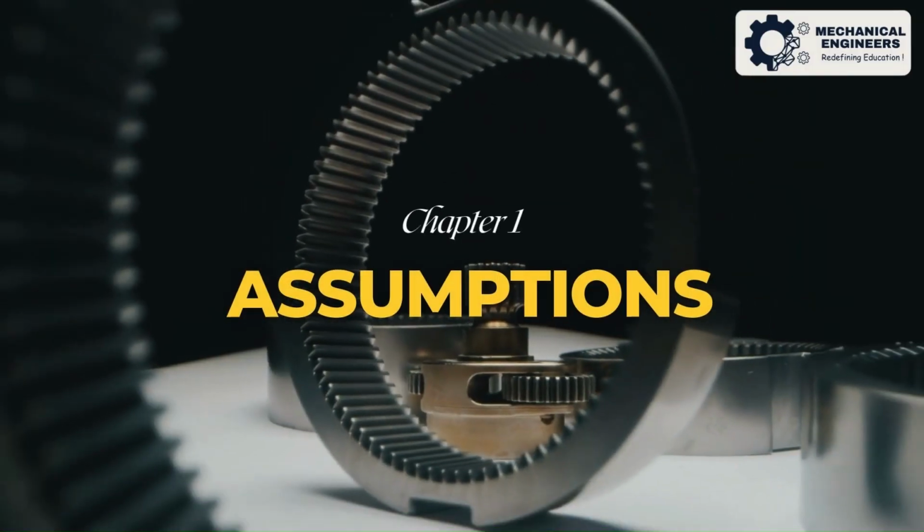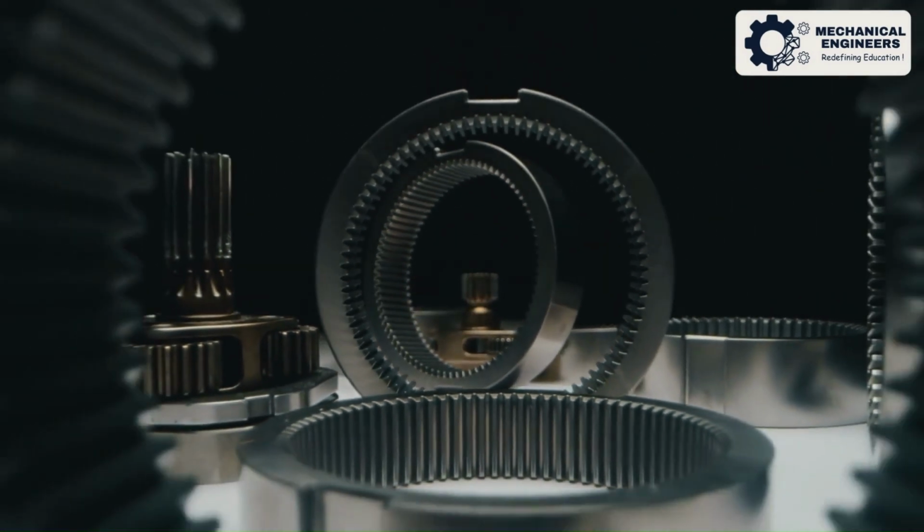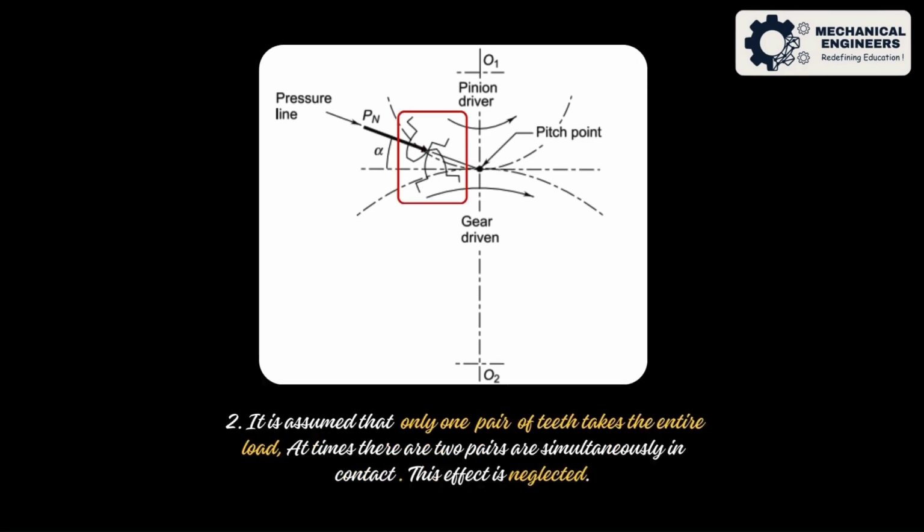The analysis of gear tooth force hinges on a few key assumptions that shape our understanding. First, as the contact point shifts, the magnitude of the resultant force, Pn, changes, but we often overlook this dynamic aspect. Then consider that typically we assume only one pair of teeth bears the entire load. In reality, there can be 2 pairs in contact, sharing the load, yet this complexity is ignored in our analysis.